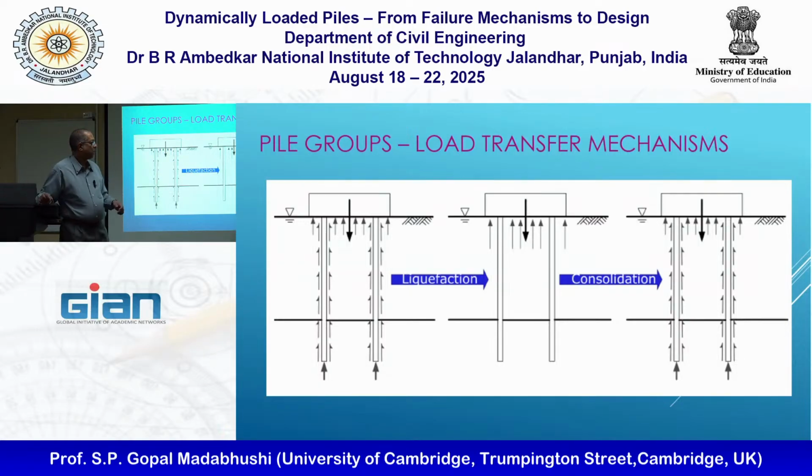Okay? So same with these piles. If you rock socket them, they'll try and find the way they can fail. That would be by buckling. If they're freestanding, they will fail by settling. If the pile cap is resting on the ground, as long as the pile cap is large enough to mobilize enough capacity, it will not allow so much settlement.